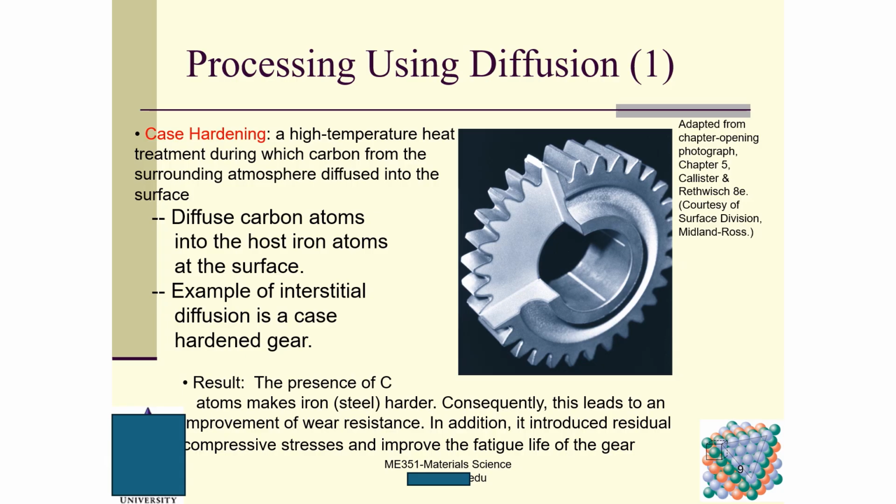Keep in mind, in order to get the benefits, you must induce this compressive residual stress instead of tensile residual stress. Because tensile residual stress is bad. Tensile residual stress facilitates crack initiation and crack propagation. As a result, tensile residual stress is detrimental for the fatigue life of the components.